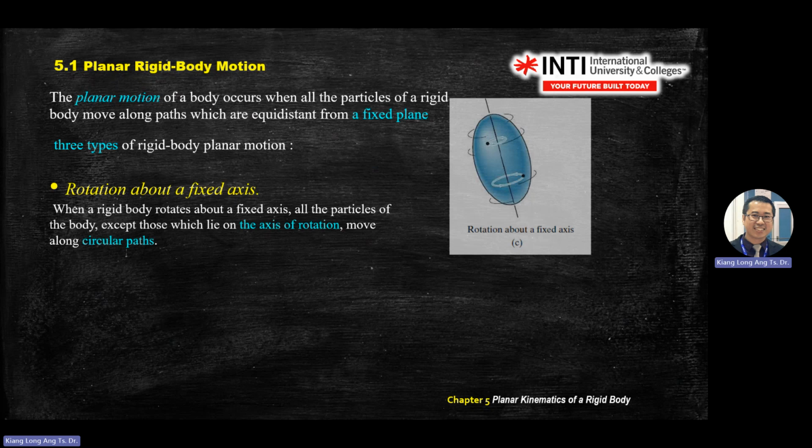Second type is called rotation. This one, particles don't have, you don't see rotation on particles. But when you look at a 3-dimensional body, you will see the second motion called rotation. Rotation must be defined by 1 line called the rotation axis. There must be an axis for it to rotate.